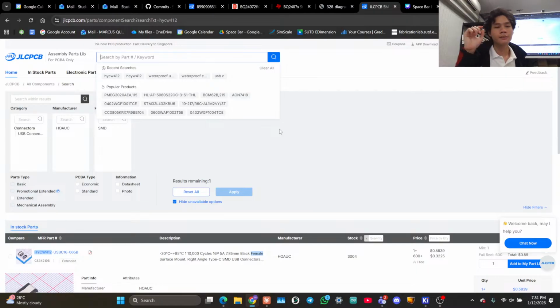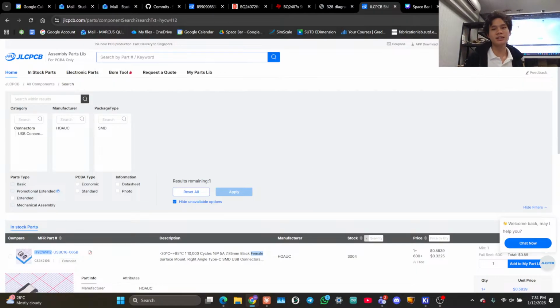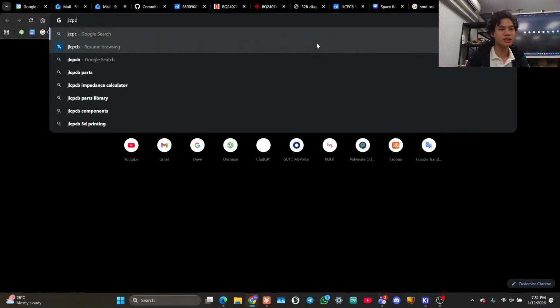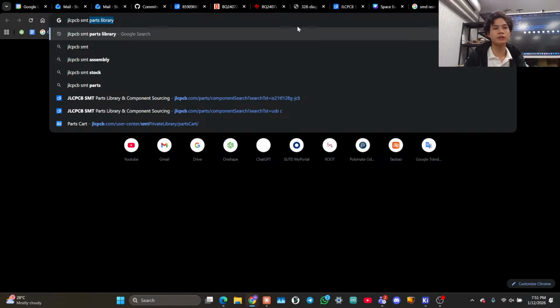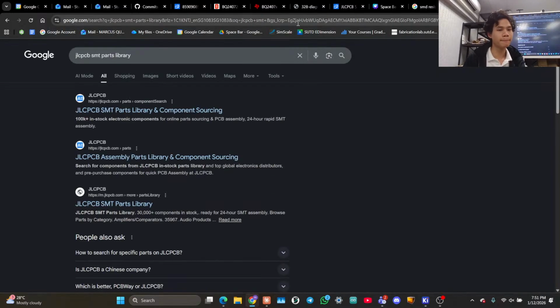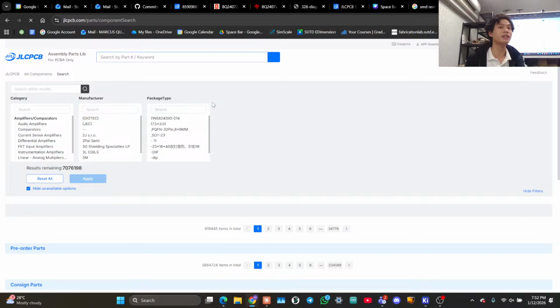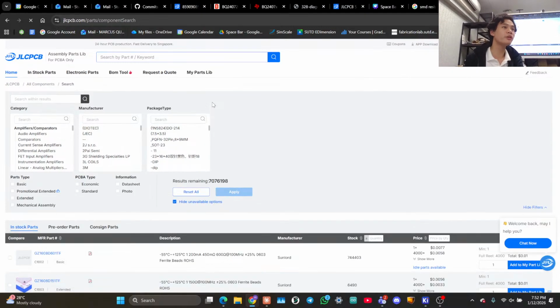So you can go to the JLC PCB SMT parts library. Literally go here, JLC PCB SMT parts library. You can click it and now you can search for your parts. This is a huge library of parts which the fabricator has available. And if you want them to solder the board for you, they better have it available, right?